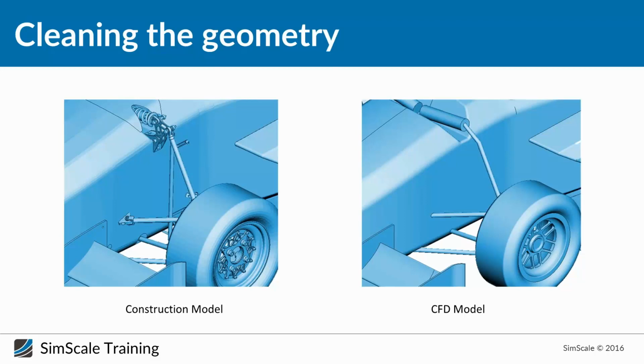Why? Because first of all, the time that you will invest in cleaning up this high detail geometry, for sure you will have a bunch of problems over there. So you will spend a lot of time trying to clean this geometry. In the meantime, you can do it better by starting from scratch in your CAD software. So for me, I would suggest to create the CFD model mainly in CAD for CFD. You will not go for the construction and then move back to the CFD. It's better to start, and of course it's clear.